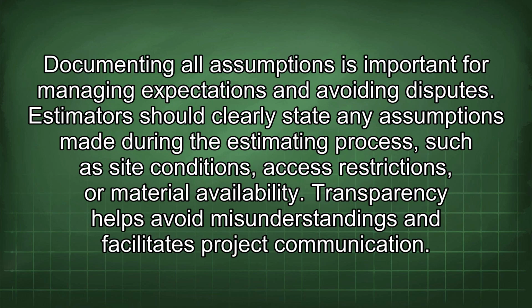Documenting all assumptions is important for managing expectations and avoiding disputes. Estimators should clearly state any assumptions made during the estimating process, such as site conditions, access restrictions, or material availability. Transparency helps avoid misunderstandings and facilitates project communication.